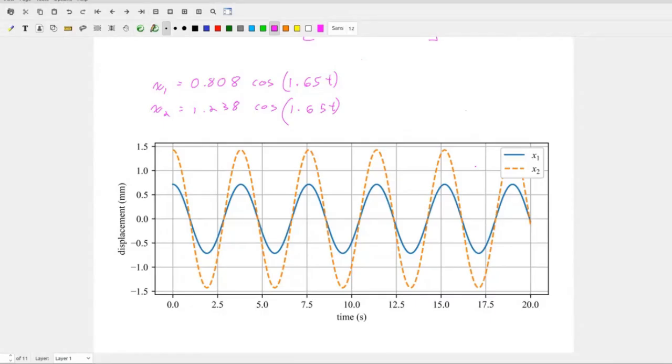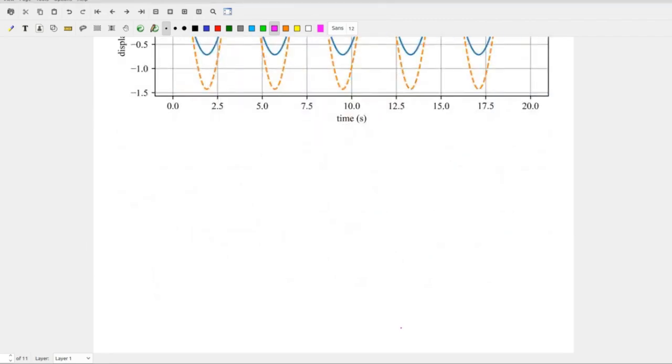This is a somewhat common approach in control systems. It gets very hard to predict a time series control of a structure, so you want to truncate the structure. Granted, you're probably not going to go to the first mode; you're going to go to the first 5 or something, but this problem is long enough to walk through without writing huge matrices. So, okay, what about our time series? This gets a general idea, but it misses the finer components that the second mode contributes.